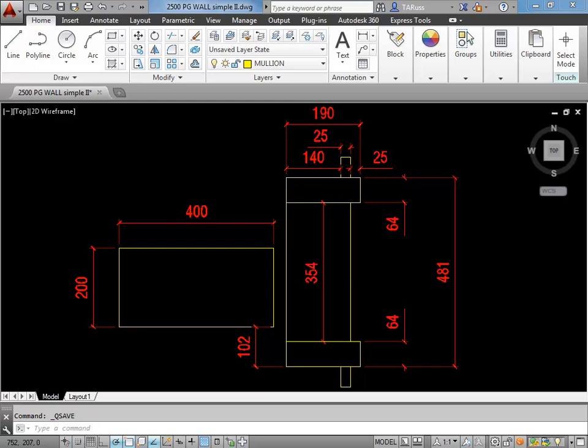And Revit totally allows that, and it works fairly smoothly. It makes sense, of course, because you don't want to redo all that work. Revit is capable of doing details with all the same sort of levels of graphic clarity as AutoCAD. But it works well, doing this kind of hybrid method also. So that's what we're imitating here. So these are obviously very simplified sort of bits of geometry here to represent the spandrel panel. But you'll get the idea from here.